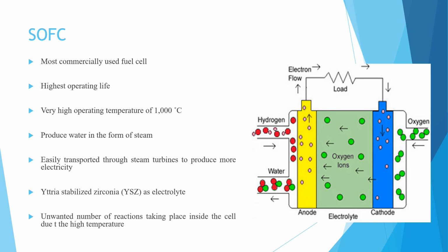This fuel cell is designed up to 100 kilowatt. At such high temperature, just because of its operating temperature is so high, a reformer is not required to extract hydrogen from the fuel, and waste heat can be recycled to make additional electricity. However, the high temperature limits application of SOFC units, and they tend to be rather large.